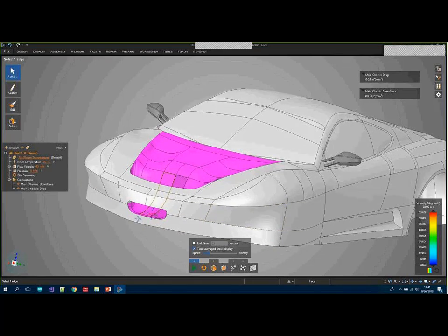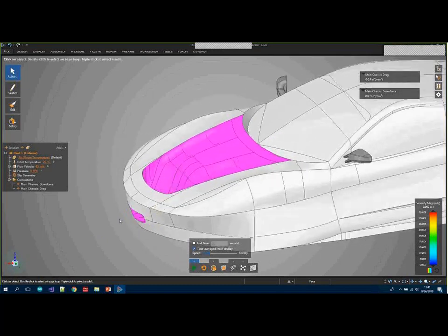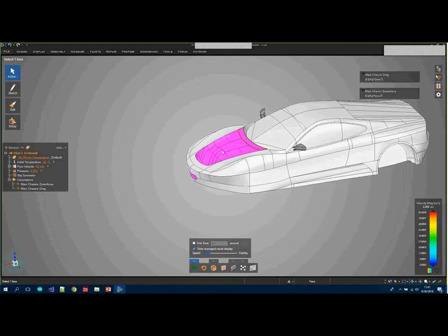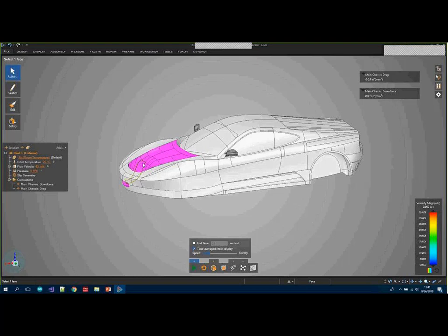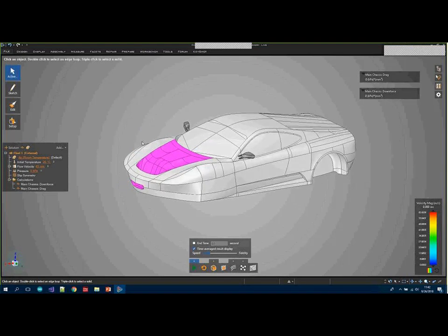But this is an inlet designed to take the airflow, allow it in and up and over the hood. Right? So that would reduce some drag and add some additional downforce. I think in the real world, the increase in drag due to this was about 2%, and the increase in downforce was about 20% over the traditional design. So fairly large increases with very little penalty. And for a performance sports car that may or may not end up on the track, those are fairly important numbers.